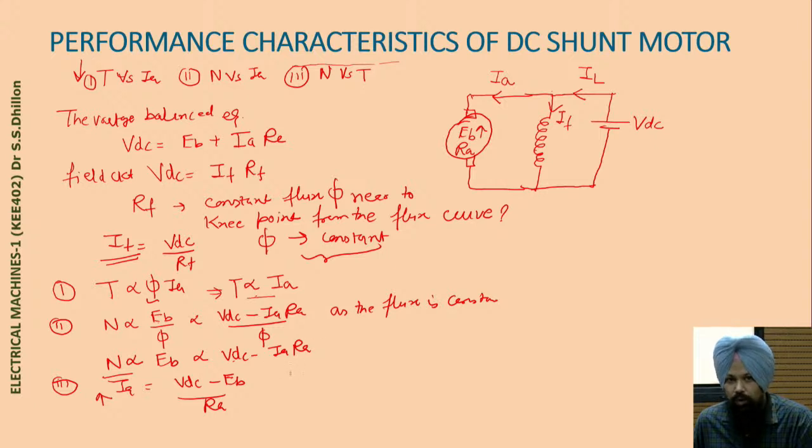So accordingly it is going to control the speed of the motor near to its previous standard speed. The deviation of the speed from its ideal curve is very small, the difference from the ideal speed is very small. That's why this DC shunt motor gives us very good speed regulation. We have good speed regulation in the case of the DC shunt motor.